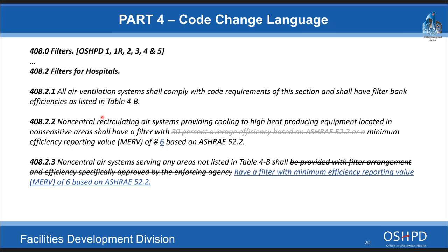Okay, so what we're doing here under filters, all we're really trying to do is not contradict the requirements in ASHRAE 170. We're trying to get ourselves really in line with that. So you see actually a reduction in a MERV rating at 408.2.2. So that's all we're doing here with these.